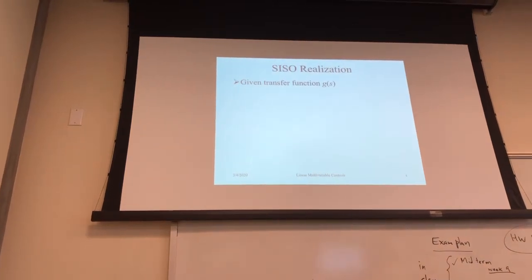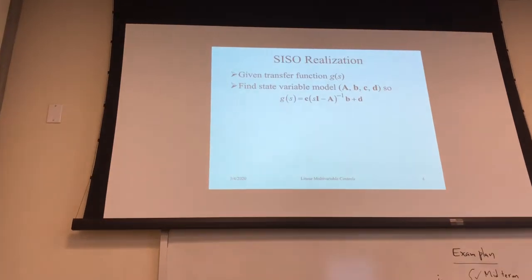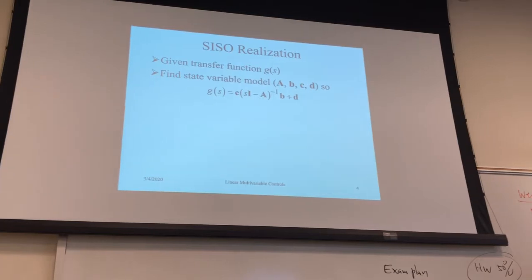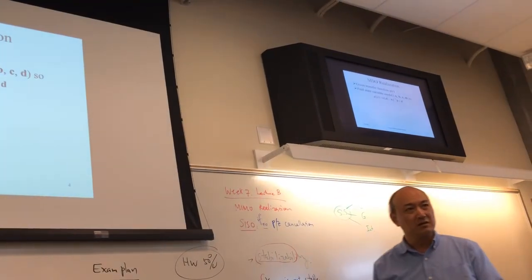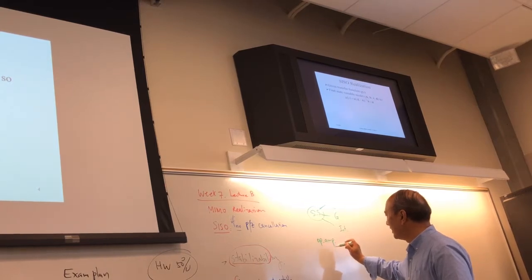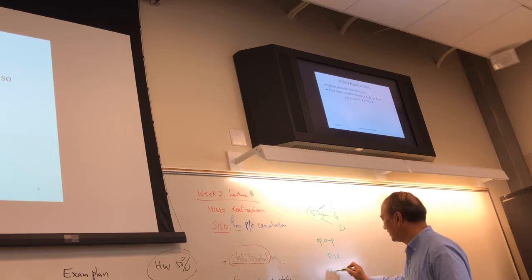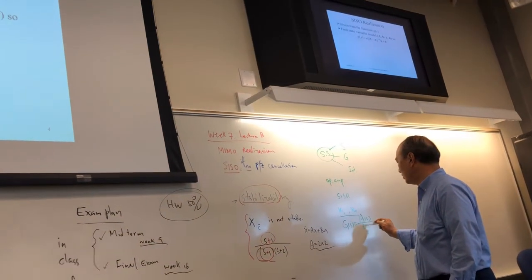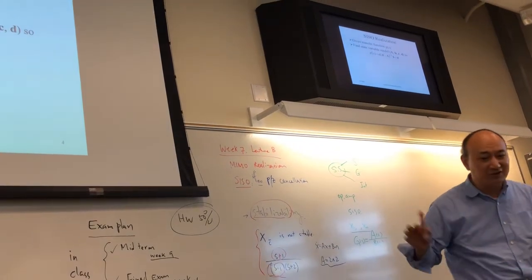We talked about it. And I think we had something original and creative in the last lecture. What's that part? I indicated that in the state space description, it is a realization based on 3 building blocks: summation, gain, and integration. Okay, integrator. And using op-amps, you can see the SISO realization. You understand how to define x1 to xn, the internal states, for transfer function G(s), which is B(s) over A(s), polynomials. Okay. So we have learned those tricks.